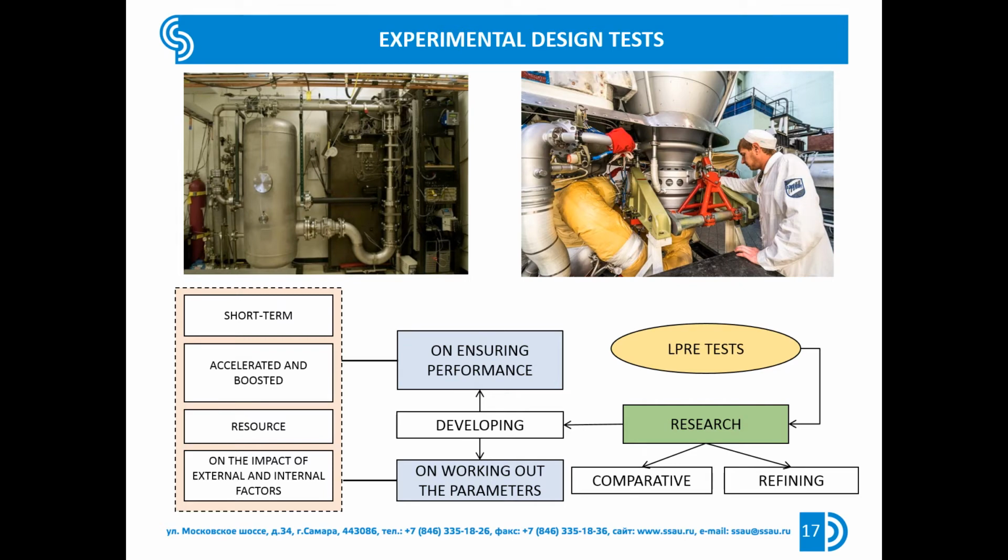After the nominal performance is achieved, tests are conducted for the service life specified in the technical specifications for the development of the rocket engine, with changes in the conditions for the pressure in the chamber and the ratio of fuel components corresponding to the operating conditions on the rocket.